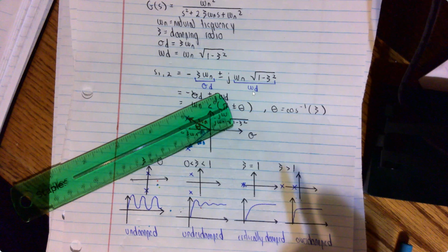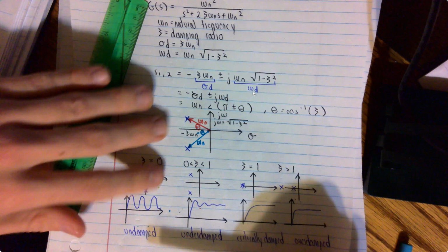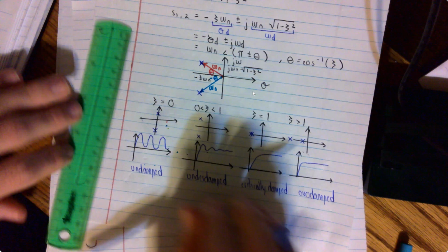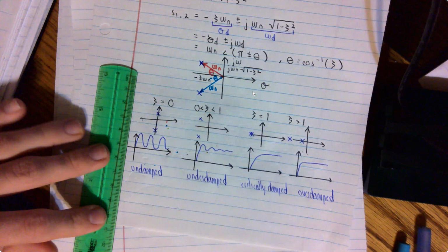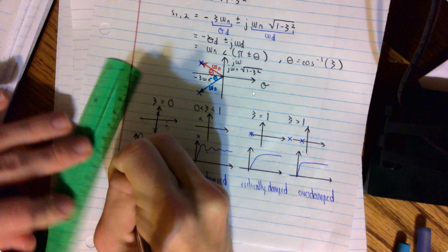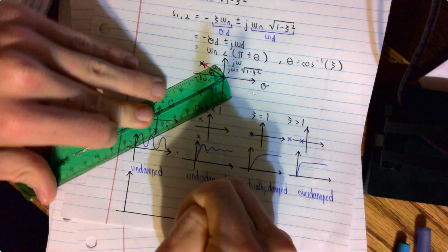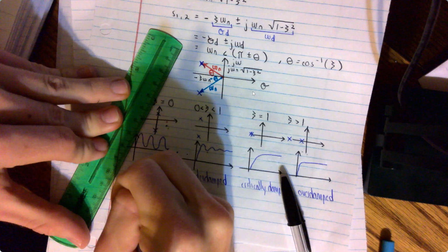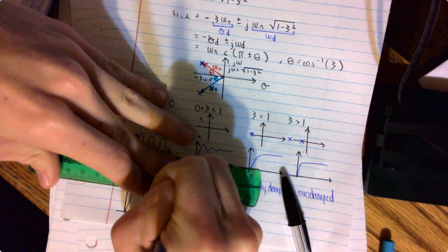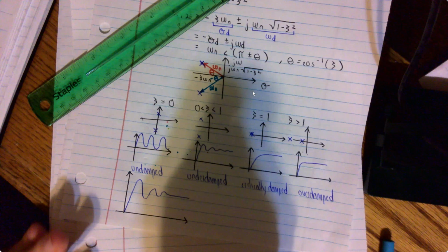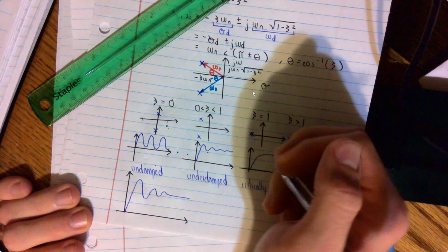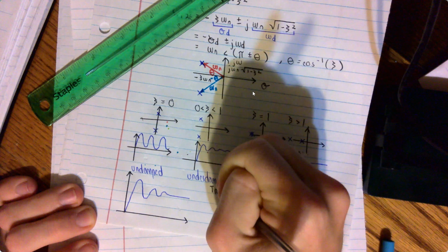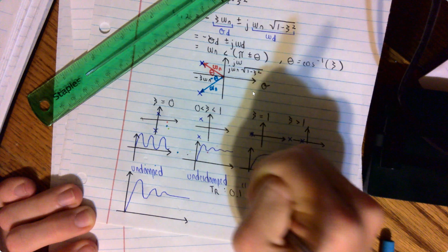Okay, so just like with a first order system, for the second order system a lot of times we like to look at the underdamped response. And that's given by the following. So the underdamped looks like the following here. And they like to talk about rise time. So T of R, remember, rise time, is basically from 0.1 to 0.9 of the final value.